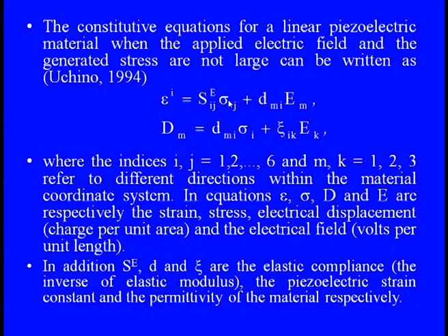And the constitutive equations for the linear piezoelectric material, when a uniform electric field is applied and the stresses generated are elastic, meaning not very large, we can directly apply the voltage field and get the strain. The strain is epsilon_j = S_ij^E sigma_j + d_mi E_m, where epsilon is the strain in the piezoelectric material, and S^E is the elastic compliance. Elastic compliance is just the inverse of the elastic modulus.